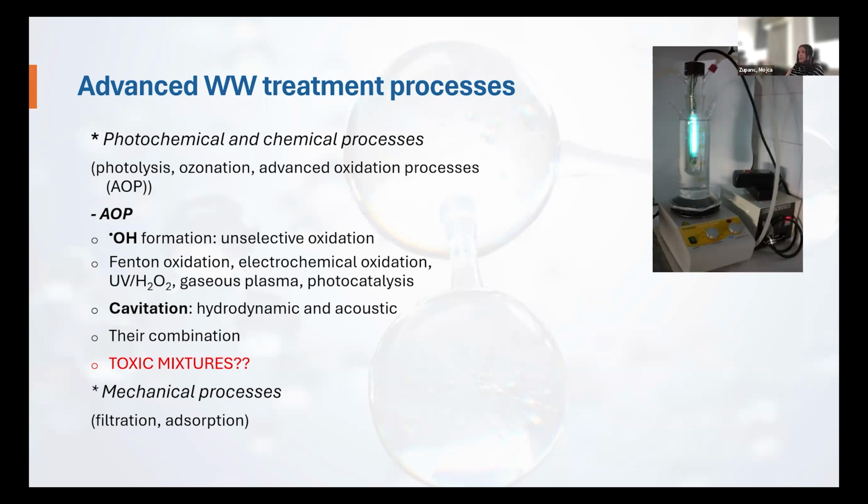Another important chemical process is ozonation. Ozonation, as mentioned before by Martin, can be a part of tertiary treatment used for disinfection, but can also be an advanced treatment. As an oxidant, ozone can oxidize organic compounds directly or through formation of hydroxyl radicals that are produced when ozone reacts with water.